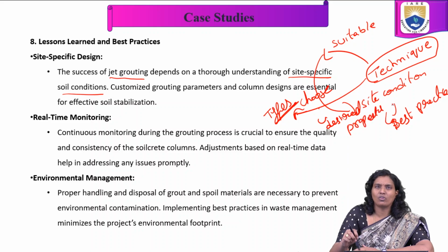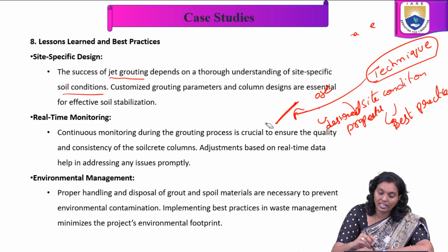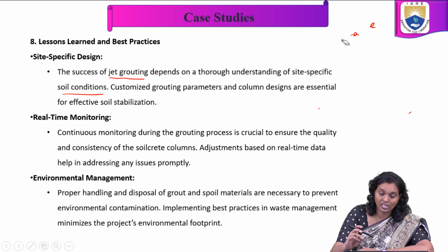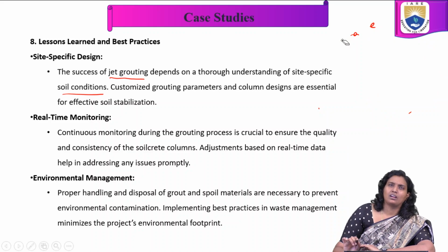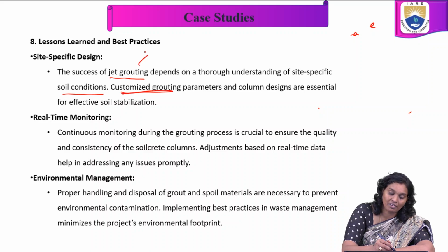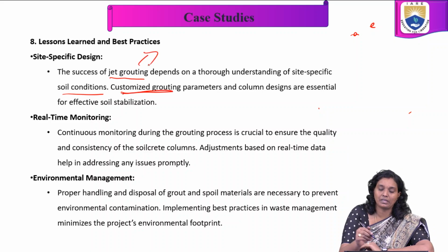So like this we have to understand the overall thing. Here jet grouting is the technique for these kinds of metro projects underground, that too in urban regions. It depends upon the site-specific conditions. This customized grouting depends upon the type of grouts, or various types we are going to choose, depending upon the requirement of the project.